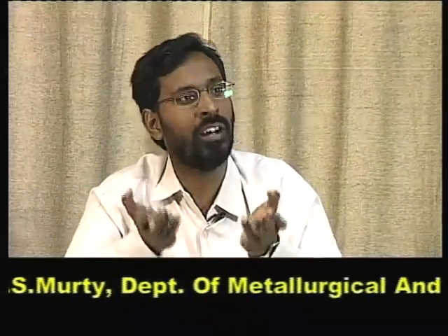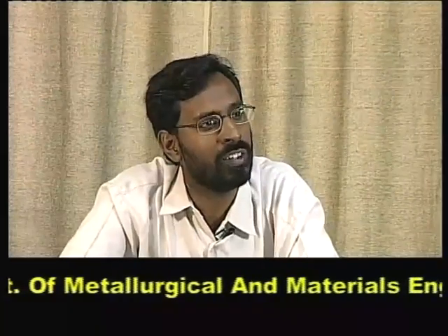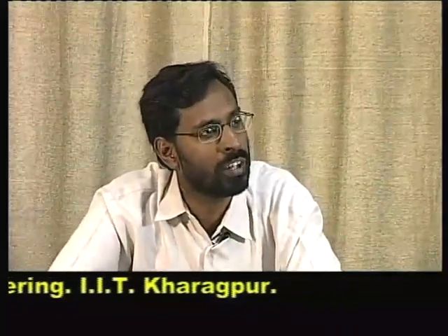One such example is aluminum titanium alloys. People want to put elements such as titanium, zirconium, hafnium, all these kinds of elements, or even iron for that matter. Iron has a much higher melting point than copper. So if you put iron into aluminum, the overall diffusivity of these alloying elements in the aluminum is very low, then precipitate coarsening is going to be very difficult, and precipitate dissolution is also going to be more difficult.